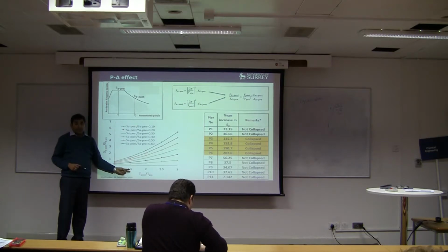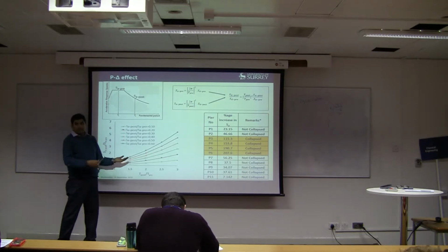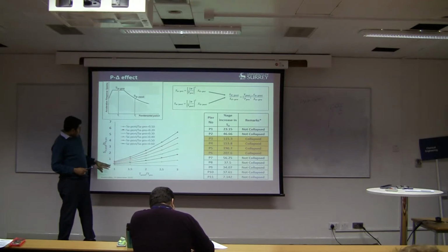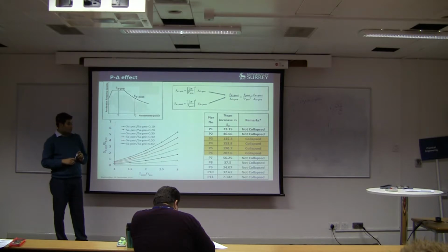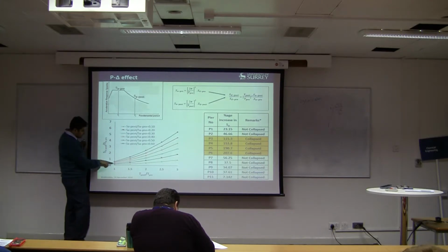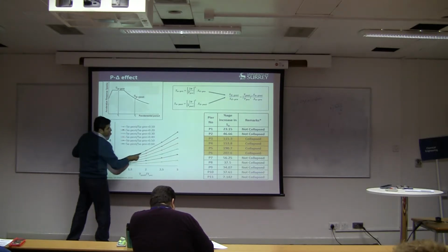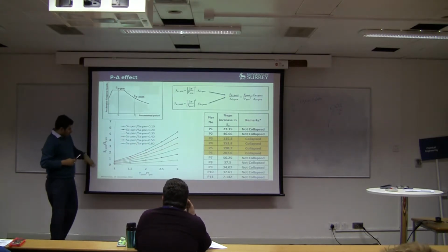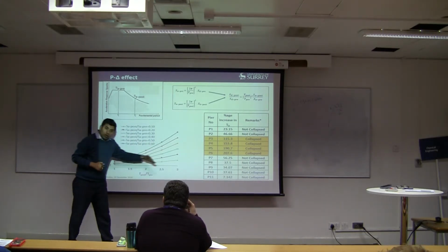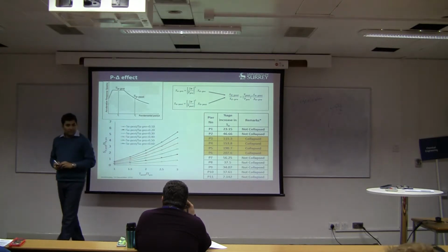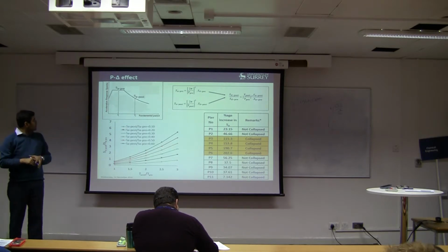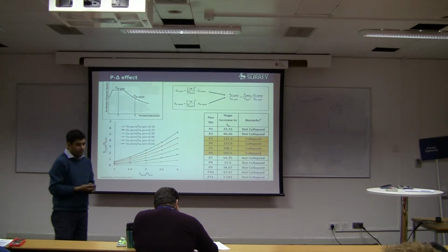If the time period increases more, you get more displacement at the top. So SD by SD is spectral displacement, post by pre. You can see this is not linear, but it starts to curve out. That means if the time period increases more, you start to get more nonlinear behavior. And this explains why the middle of the bridge fails. Yeah?